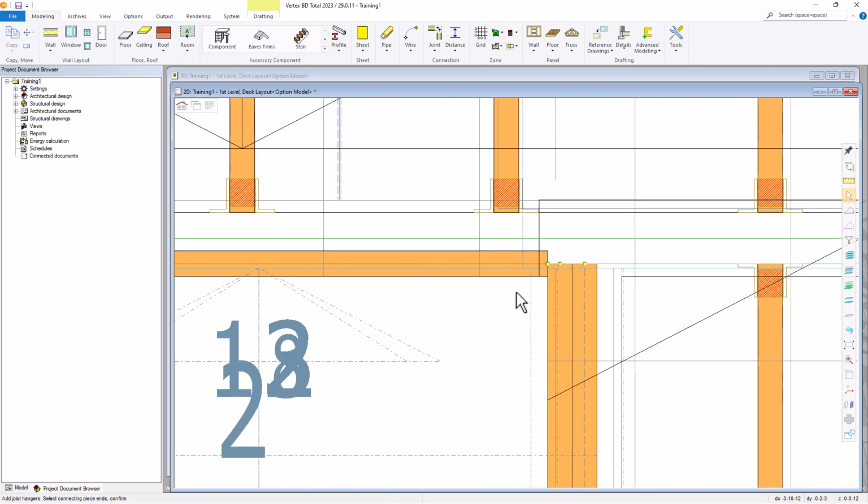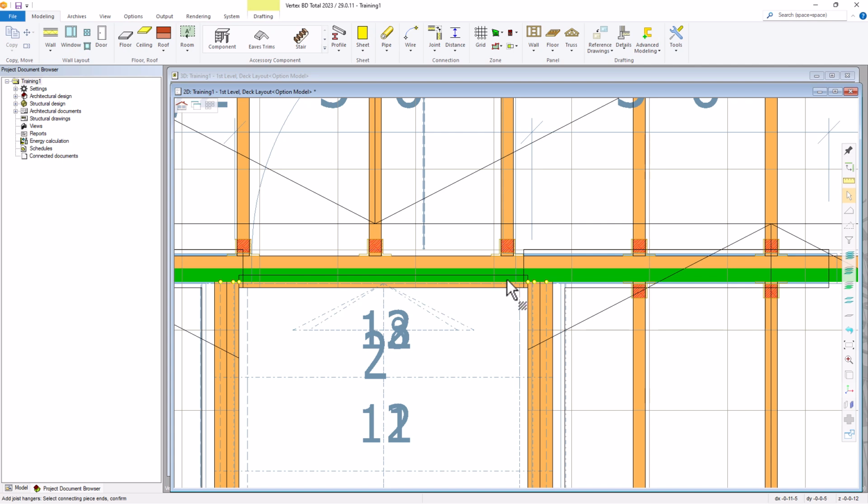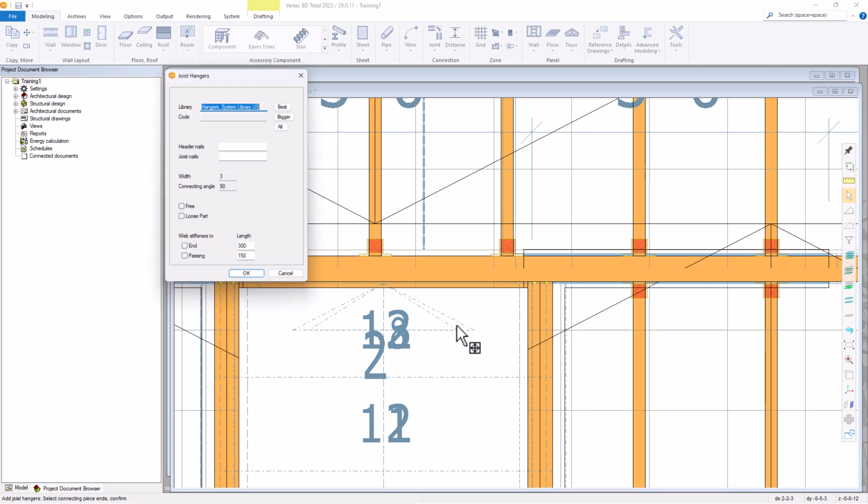When we zoom in, you might have a third dot. That's because there is an additional horizontal piece overlapping the flush member, and the end of that piece was also selected by the crossing window. Click on the yellow dot to unselect it. And we can unselect, let's see, that one. So we should only have those dots. We'll come back and delete that piece out later. So hit V to confirm.